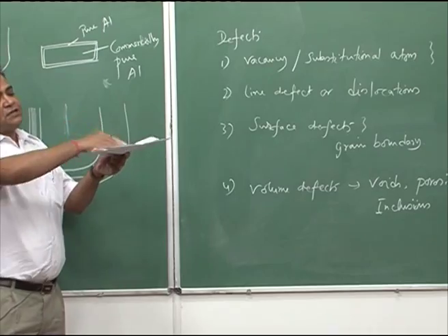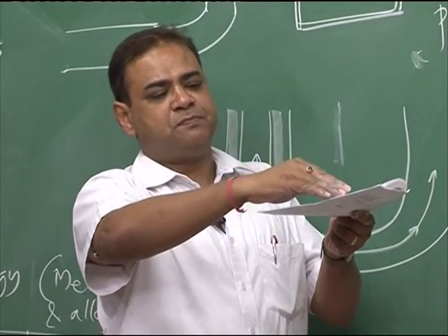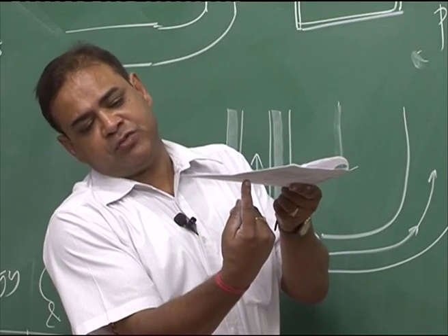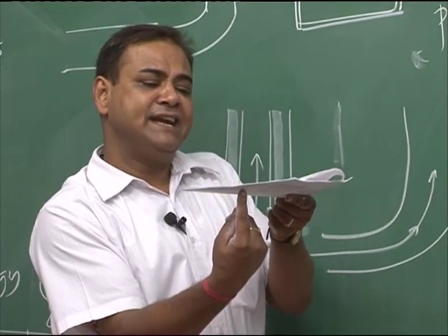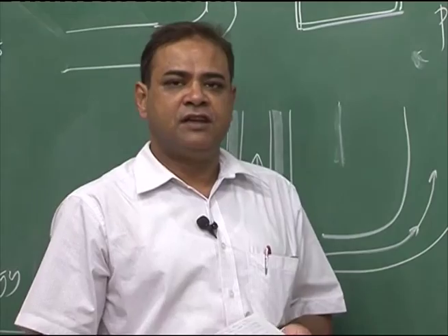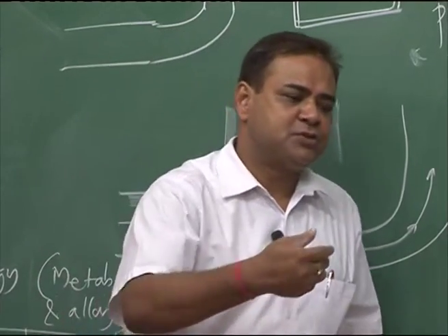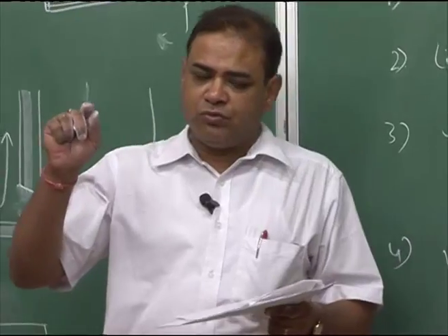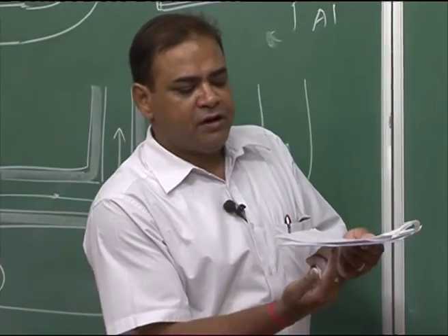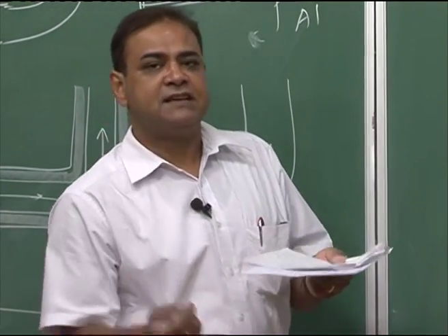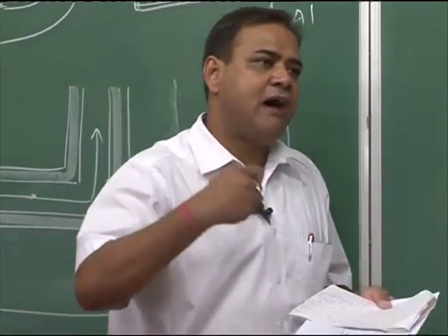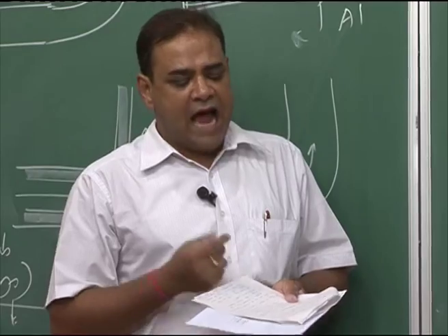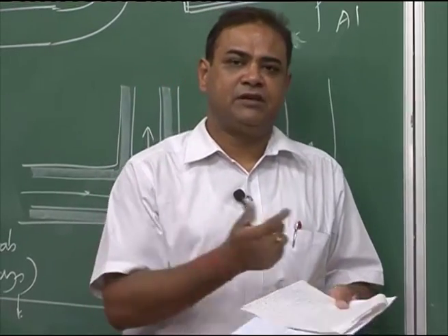This is let us say the surface of the metal which is etched, and this is another dislocation which is coming and ending out on the surface. Then if we expose it to chemicals, then that dislocation which has ended on the surface, that section will have higher tendency to get attacked by the chemicals, and that attack is of electrochemical nature.